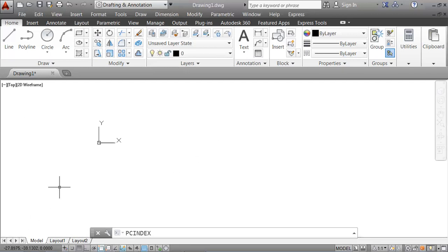This is telling us that this is automatically called 0, 0. 0 in x, 0 in y, right? That is the absolute method. It means that if I want to draw a line 100 millimeter, starting from 0, the line will be connected to the UCS right here, right?